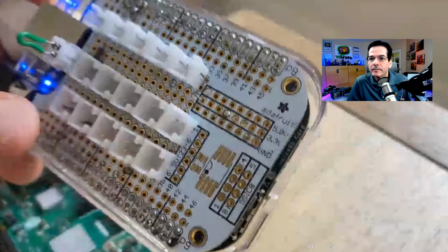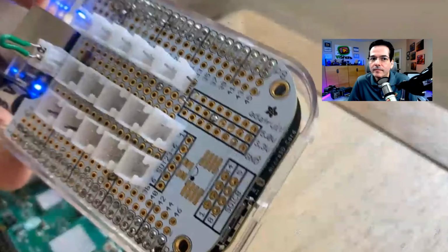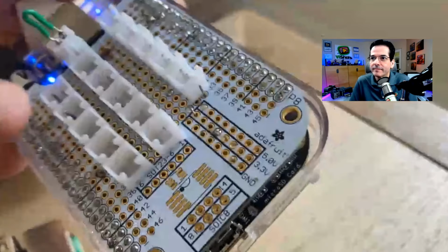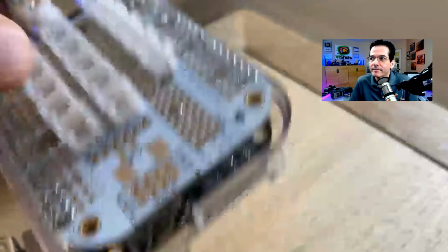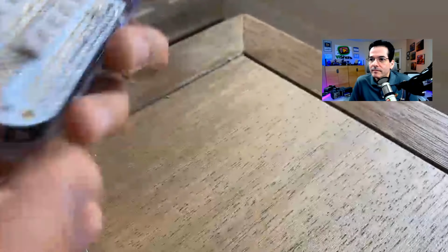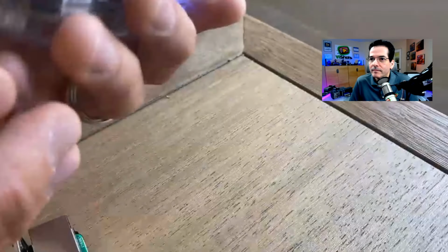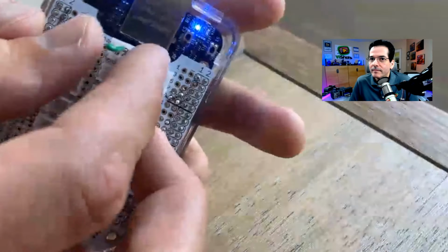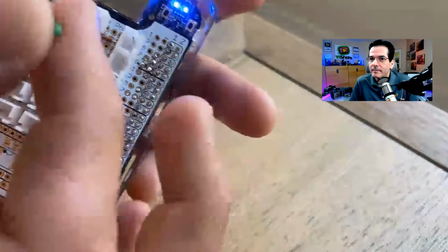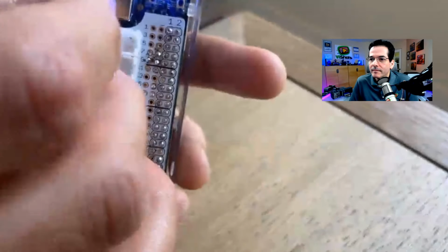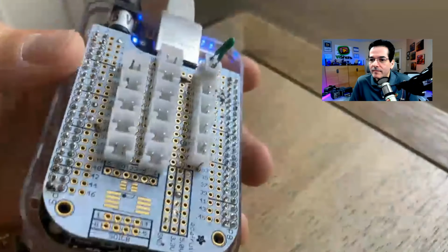So I have, and I'm hoping you can see my screen. Yes, we can. Okay, great. So I have a port for each of the 16 zones in my house, and I had to do soldering to wire pull-up resistors and then connect those to the digital lines. And then just for the sake of this demo, I have this little jumper cable that I'll use to simulate closing a window or door sensor. So by default, you'll see that all my windows and doors are open in this demo.